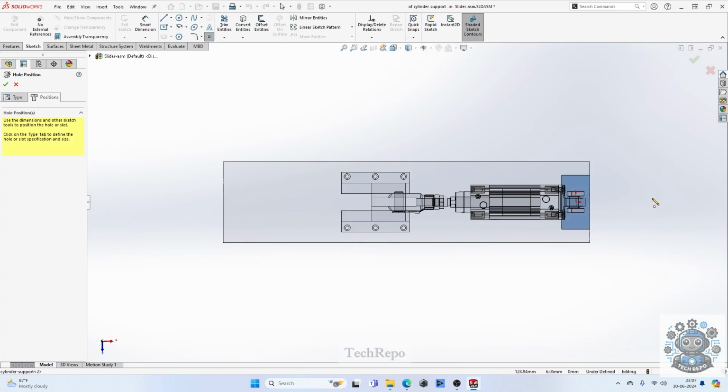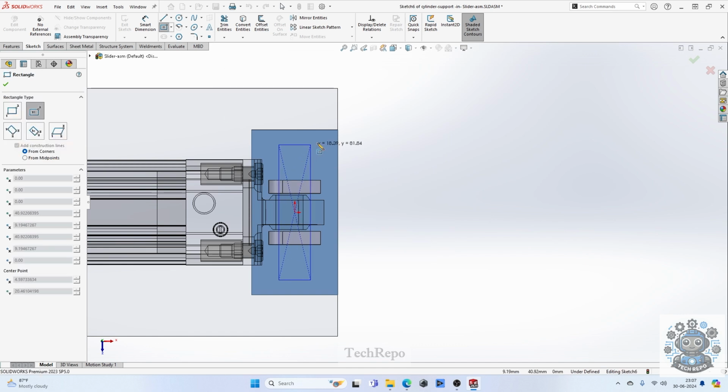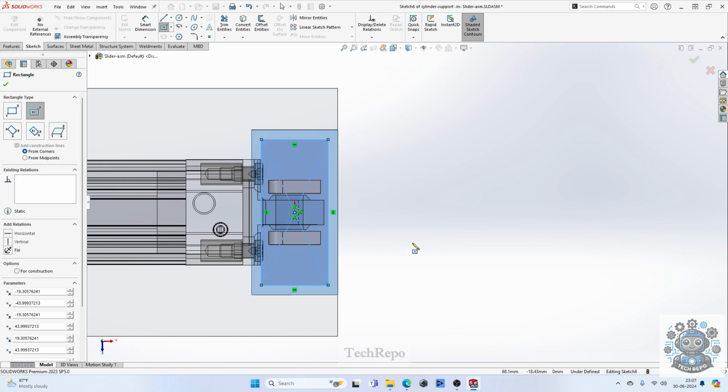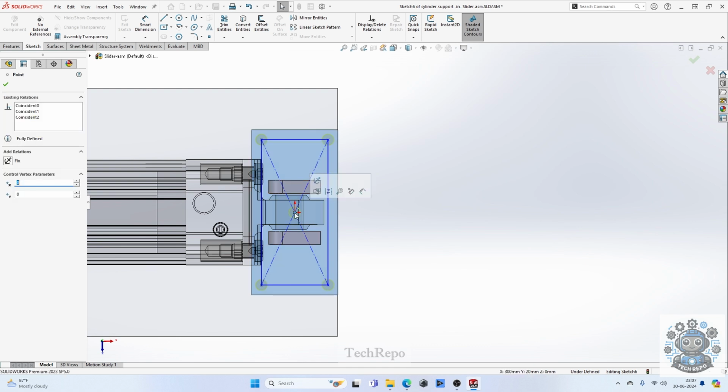And there is also one more thing: whenever you define an assembly you should try to have the same fastener size as much as possible, because practically during maintenance the engineer would probably carry just 2 or 3 Allen keys, so maybe M6, M8, M10, and for bigger assemblies you might carry M12 as well.